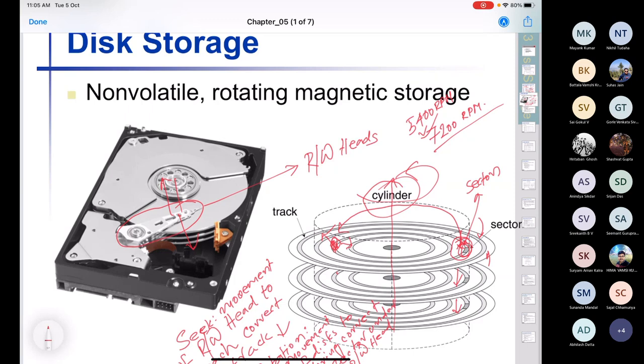So typically you will find that although your microprocessor chip can work at a voltage of say 3 volt, 3.3 volt is very common, and the internal circuitry of the microprocessor probably works at less than 1 volt, 1 volt or 0.75 volt or something.